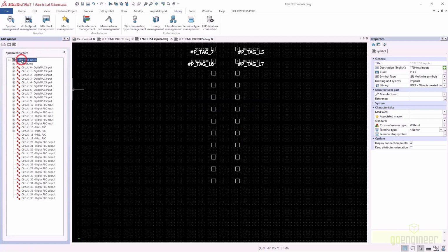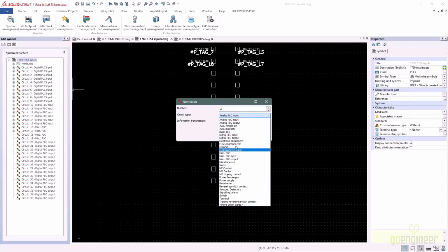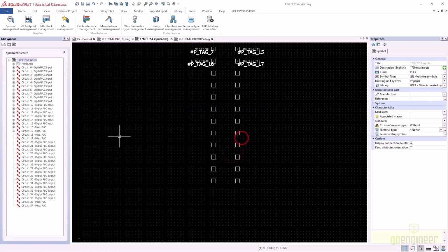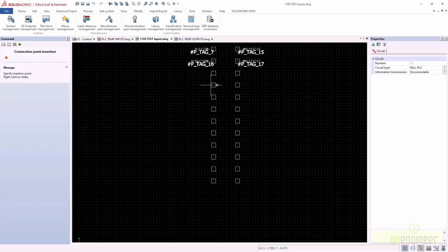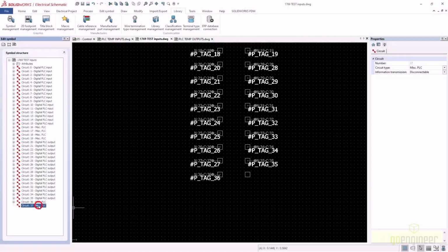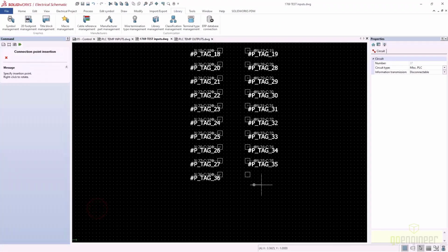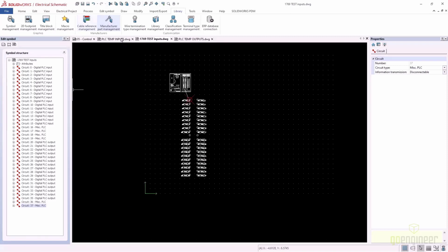So if you are at least handling this by doing the configuration of the symbol, you are able to control where those attributes are going and which circuits are which. So again, we know that these connections are going to be dropped in, skipping one space. We'll go ahead and start. I moved ahead just a little bit here to finish up and drop that next one. Now, we have all of this here. Let's look at the attributes that we have from our temporary symbols.